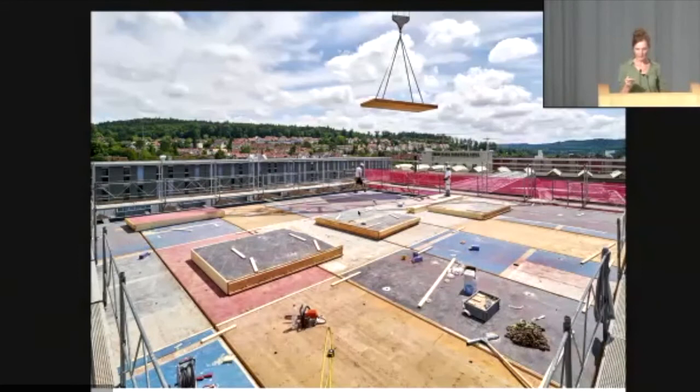So with them, we agreed on a way we can do this. In Switzerland you have a Systemnachweis, that's what it's called. For the energy code, when you build something new or change something, you either have to prove that this window is good enough, and the wall, the ceiling and the floor are each good enough, fulfilling these individual numbers. Or you can say, I look at this building as a whole, and if my window isn't good enough, I can make the ceiling a bit better, as long as the whole system functions. That's the way we approached it.